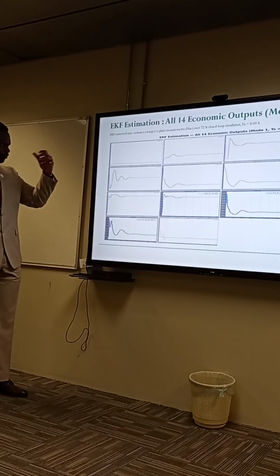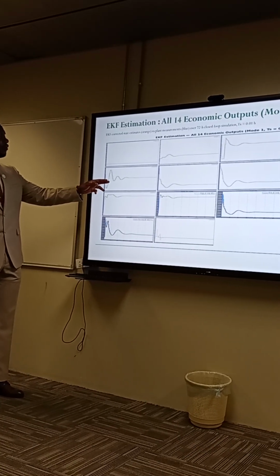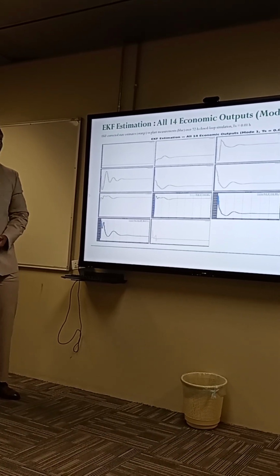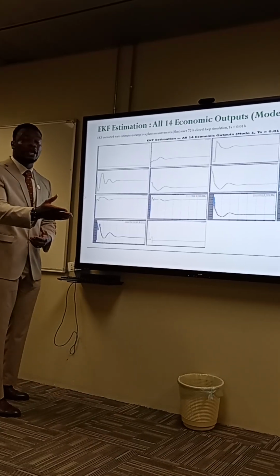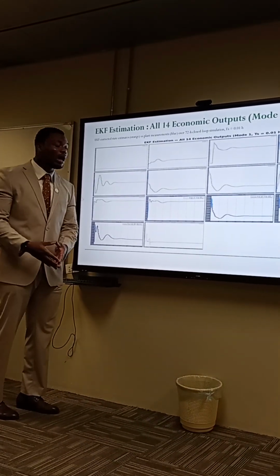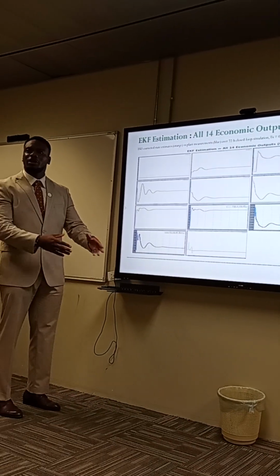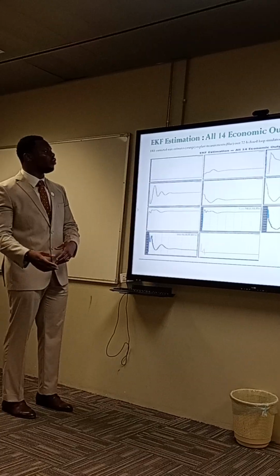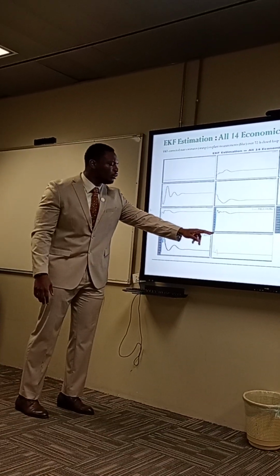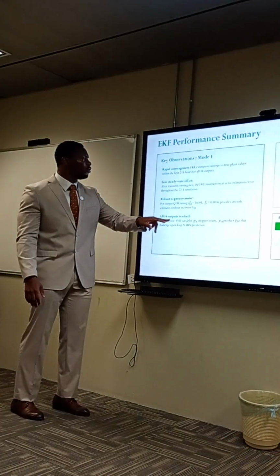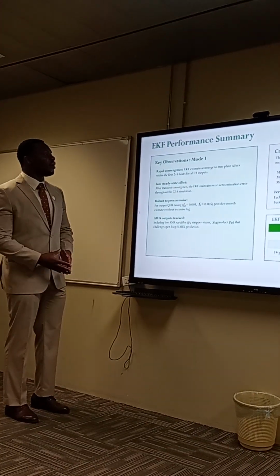And of course, you can see here that we're doing it over a 1 hour interval. So our Kalman filter predicts every 1 hour and updates every 1 hour, and then you can see that regardless of where you started off, they converge, even with the sampling time of the process at 0.01 hours. So basically, the EKF performance is pretty good.